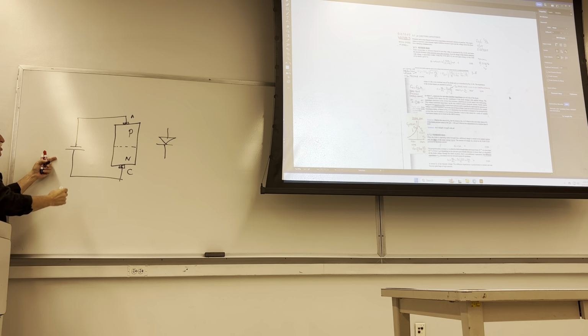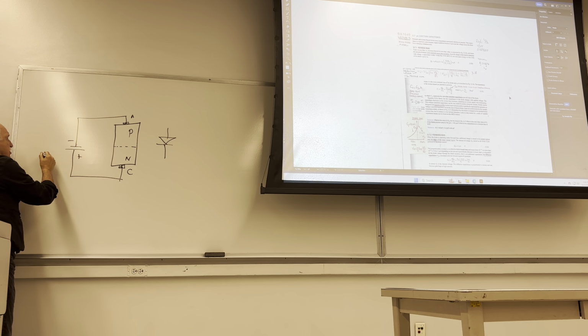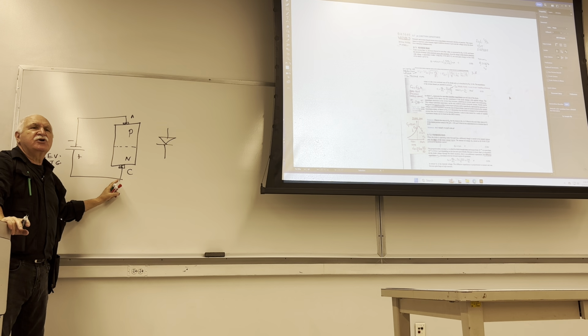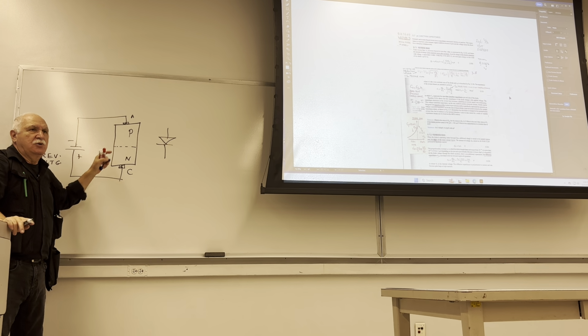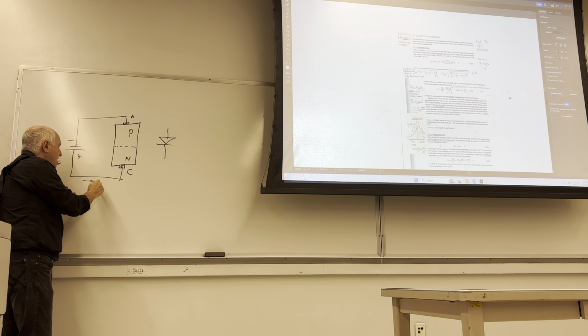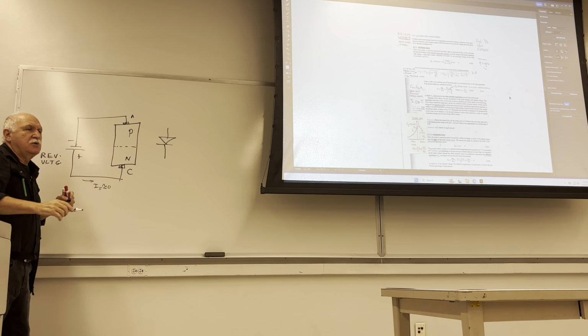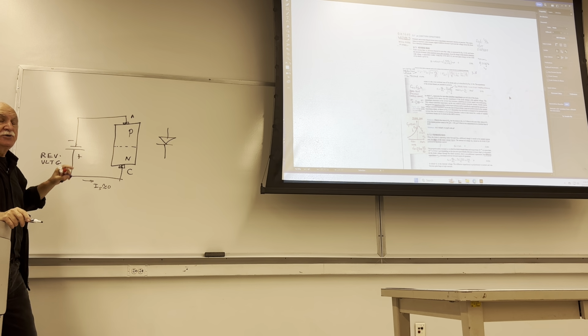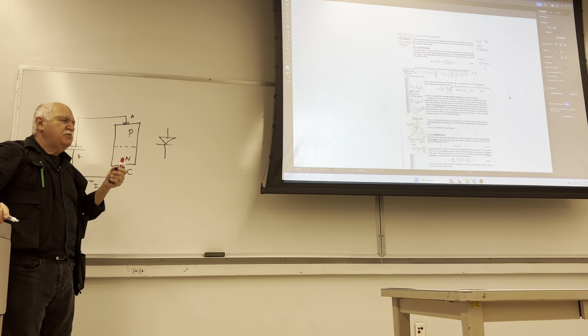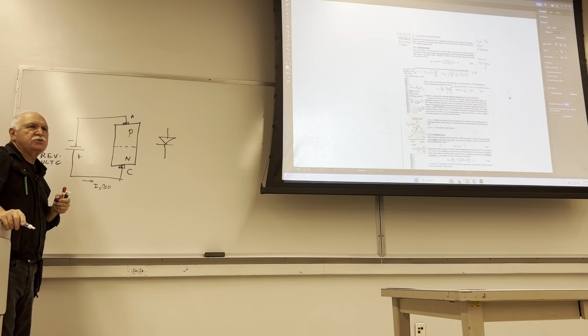If a voltage is applied in reverse, there is going to be no particular current flowing into the diode. In other words, the current out of the power supply will be practically equal to 0. There will be a reverse current in the diode, known as the reverse saturation current, practically so small. It won't do anything.